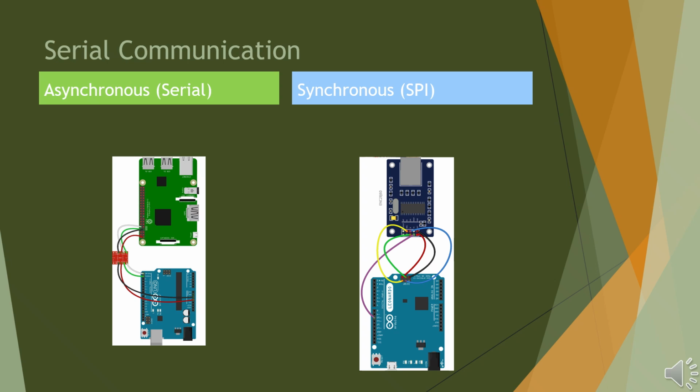The wiring connections are VCC, 5 volts, GND, ground, SCK, pin 13, MISO, pin 12, MOSI, pin 11, and CS, pin 10. During operation, when the Arduino sets CS low, communication begins. Each clock pulse shifts data out on MOSI while receiving data simultaneously on MISO. When the message is complete, CS is set high, ending communication.